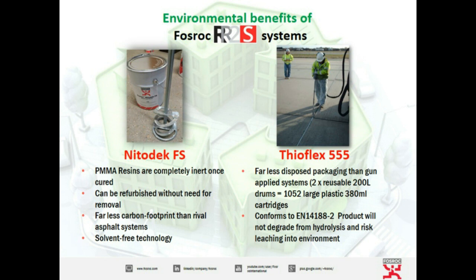the project timings. For example, something like the Nitec FS, not only are they inert once cured, but unlike epoxies, you can in essence part mix material. So you're not having that dilemma where you're mixing half and putting half in the skip or wasting half. No, you can part mix, put the lid on and go again. It also benefits from the solvent-free technology.